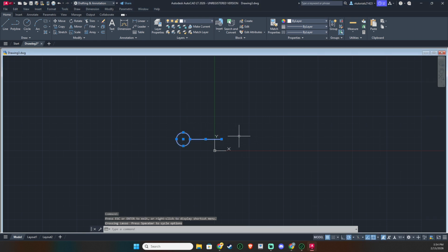First, open AutoCAD and load the drawing you want to work with. It's always a good idea to make sure your file is saved and that your units and layers are set the way you like, so the new copies land exactly where and how you expect them. Next, select the object you want to array. This can be a line, a block, a circle, or even a small group of objects. Pre-selecting helps the command run smoothly.